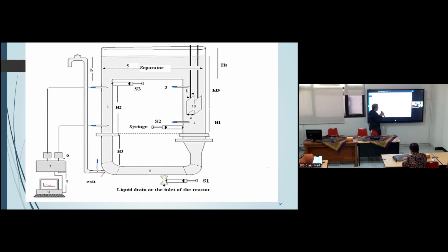I have to analyze the flow by analyzing the signal here. For example, if the tracer takes time to arrive, maybe we have two paths, here and here. This is why I do this study: to see if this batch reactor can work as a continuous reactor, or if I have to change it. Okay?